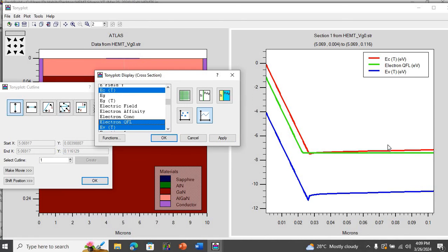So as we can see, we are applying a positive voltage to the gallium nitride layer, a negative across the gate. So we drag down the gallium nitride side of the energy band diagram, and now we see more band bending under biasing conditions across this interface.